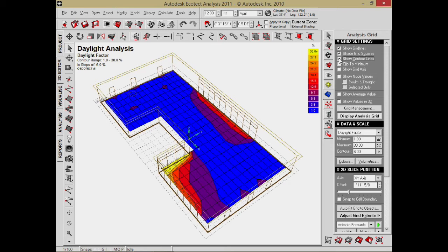This isn't so bad. This is bringing daylighting in, but let's think about it. This is actually 30% of the outside daylight. So let's talk about that. Daylighting factor is a percentage of the outside daylight. Okay, and 30% sounds like it's pretty good, but another way to look at it is something called just the daylighting level. And that's almost like 100-watt bulb versus 60-watt bulb. It gives you an equality of the intensity of the light into something that's a little more easy to relate to. It actually is completely related. It's just a mathematical formula.